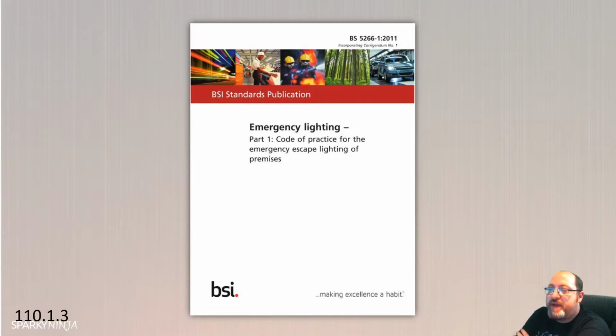So, by it being supplemented, it means BS 7671 may need some support from a finer area that will have either more technical regulation, more technical information, more technical standards, or just a coverage of scope not covered in BS 7671. So, some examples here. Well, here's the obvious one there. Emergency lighting, BS 5266. So when we think about emergency lighting from our BS 7671 perspective, it will tell us about the wiring system needs to be segregated from all other lighting and power.